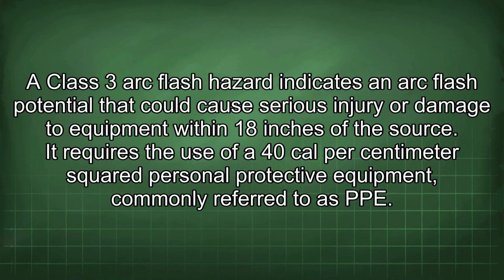Class 3 arc flash hazard indicates an arc flash potential that could cause serious injury or damage to equipment within 18 inches of the source. It requires the use of 40 cal per centimeter squared personal protective equipment, commonly referred to as PPE.